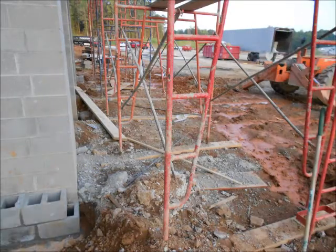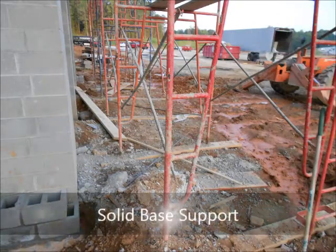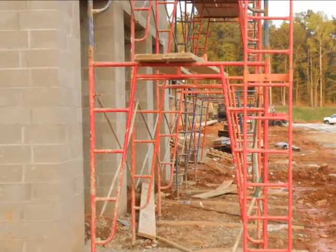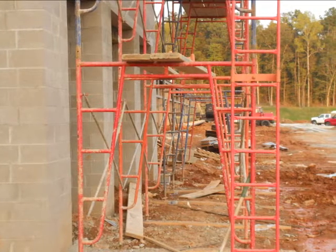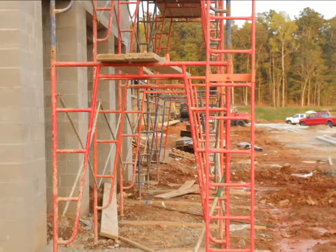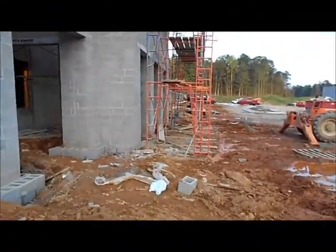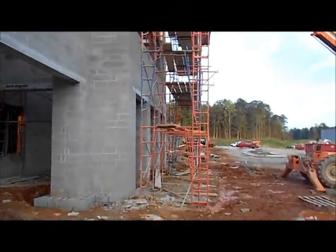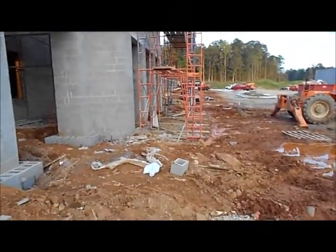The first section of the scaffold must be set in the final position and on a solid base. Component pieces must match and be of the same type. All wood used must be scaffold grade wood. All platforms must be at least 18 inches wide. Scaffold height can be no more than 4 times the distance of the base unless ties or braces are used.